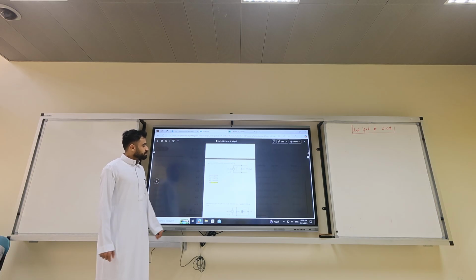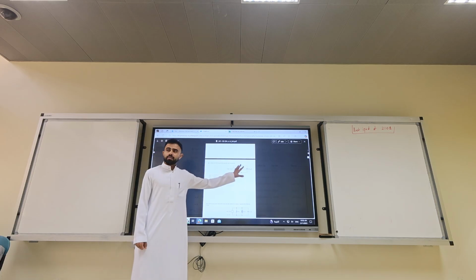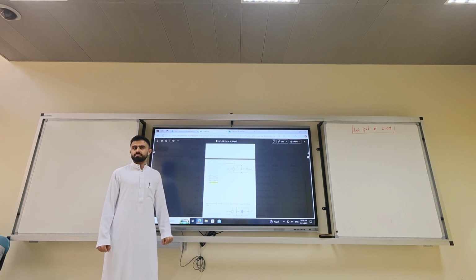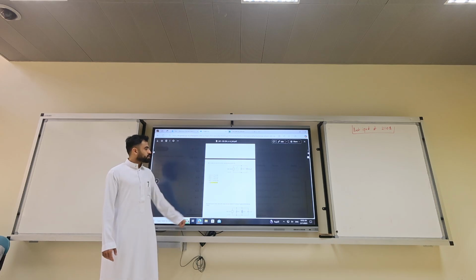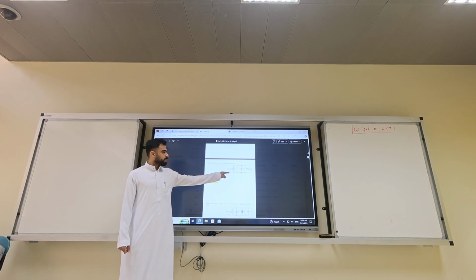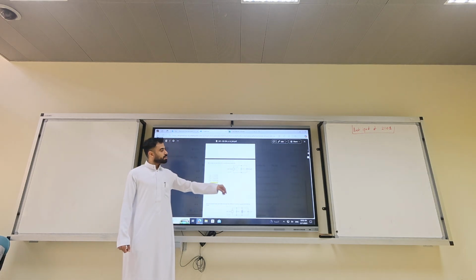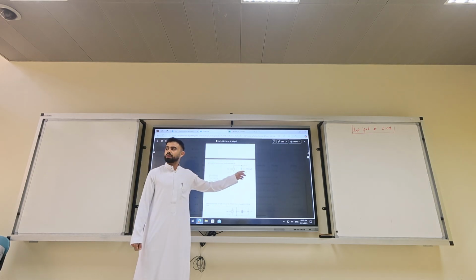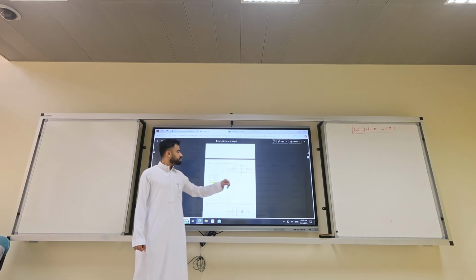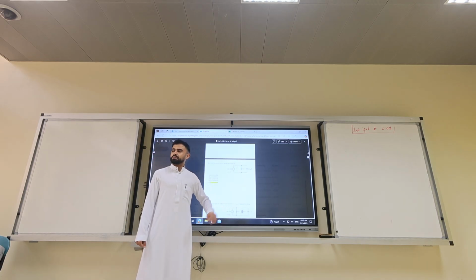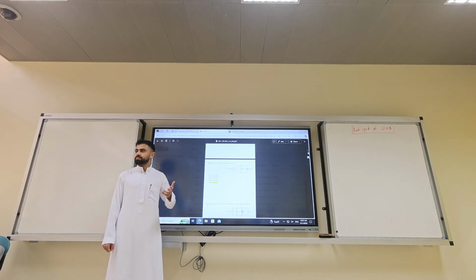Now, looking at this problem, what chapter? Chapter 5. Because we have omega, we have to convert 10 microfarad to 1 over j omega C. And then we use our favorite rule, CDR. Once you get the CDR, you can calculate the complex power.